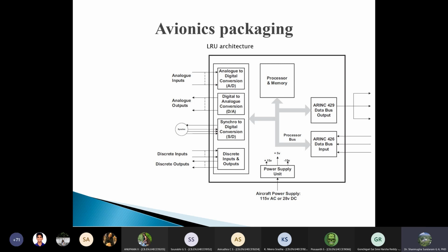It creates a transduced representation of the angular position and angular velocity of the shaft as corresponding electric signals. While they still remain in analog form, they need to be converted into the digital equivalent using encoders and decoders. The delivered signal is proportional to the sine and the cosine of the shaft angle. So the synchro to digital converter, SDC, is used to convert these signals to the corresponding digital output, which corresponds to the shaft angle and the shaft velocity.